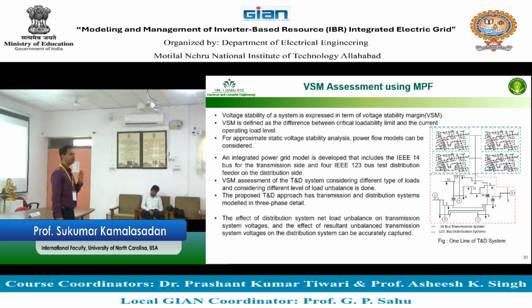So if you plot the PV curve for the entire system, will you see the changes in the voltage with respect to the changes in the power? Yes. So can you see that when the power changes, what happens to the voltage at that point? Yes. So, can this PV curve be studied for slow moving power with respect to slow moving voltage? Not very fast change in the voltage, not dynamic. So you have to be careful seeing that PV curve. Once you have the PV curve, what is that difference you can get? You can see the point at which the voltage on an electric grid collapses when the power changes.